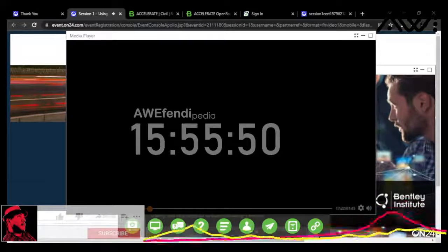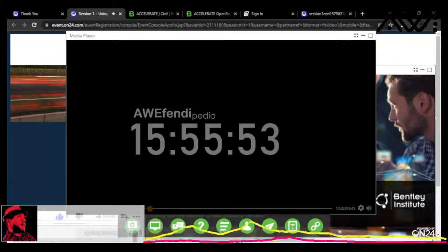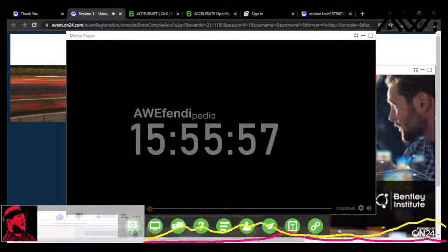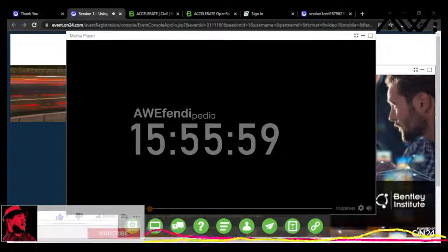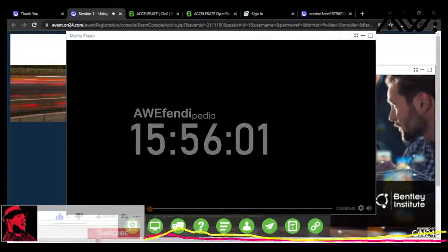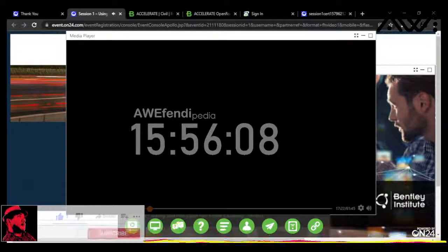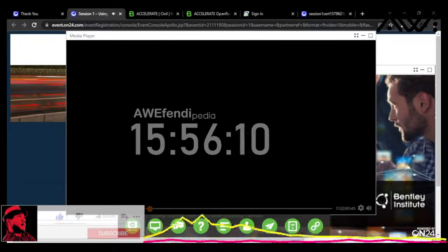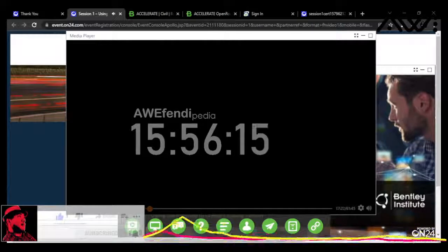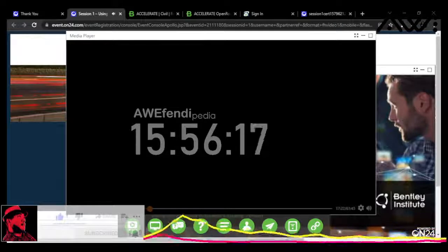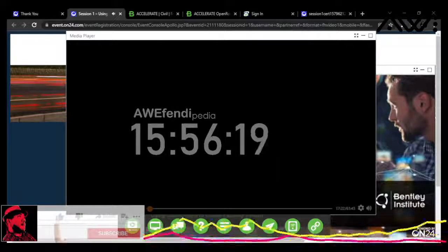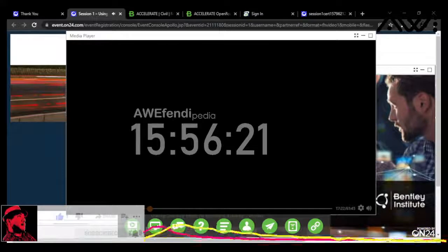So knowing that information about what is in the raw file that we're going to import, I want to look at the settings and make sure that I've set it up correctly to import that information. So first of all, in the OpenRoads standards, the first thing I want to look at is in the library section. And this is going to be the DGN libs that we've told it to load in the workspace. So we'll expand that here. The first time we open it, it takes a couple of seconds.